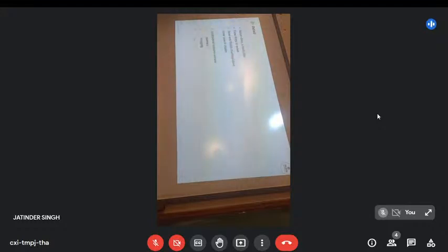With the detail of microfluidic systems, because there's so much technology, it's always good to think about what the device actually looks like and how it works. I do a lot of scribbling on a notepad, drawing the chip and arrows where forces go. How are the fluids being manipulated? Is it gravity driven? Is it electroosmotic? Is there a syringe pump sitting somewhere? Is it peristaltic? Does it matter how the flow is driven?